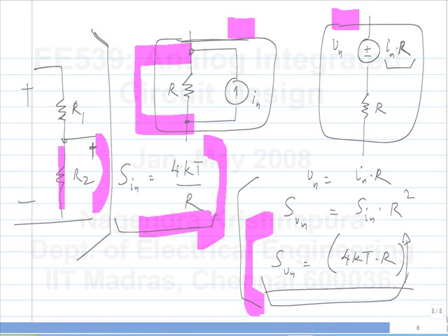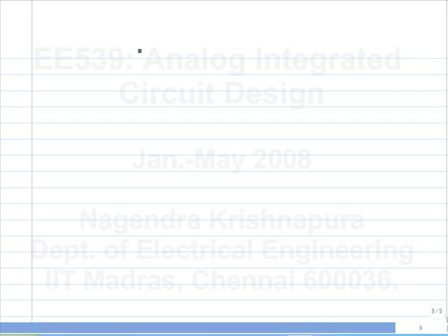The two are equivalent, that you can see straight from the circuit analysis models. This is exactly equivalent to this. But also, the two are measuring different quantities. One is measuring current noise, the other is measuring voltage noise. So, there is no contradiction if one of them increases with the resistance level and the other one decreases with the resistance level. If we want to find out the noise in any circuit, let's say we have only resistors, or at least we have noise models only for the resistors. So, every resistor is replaced by the model, which depending on convenience, you can either use the parallel model or the series model, and you calculate the transfer function from each of the noise sources to the output.